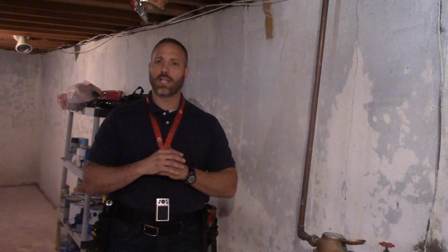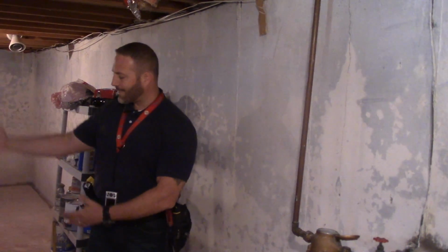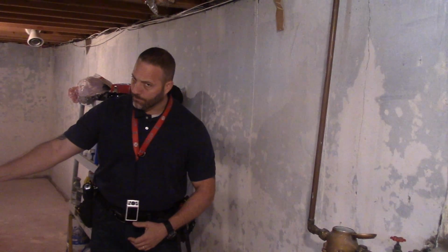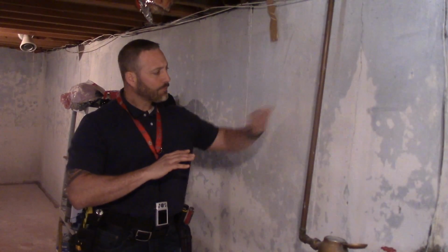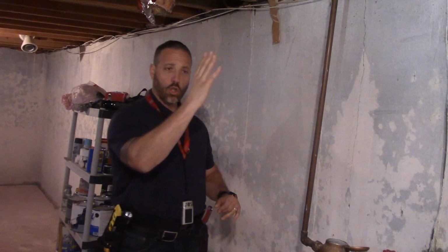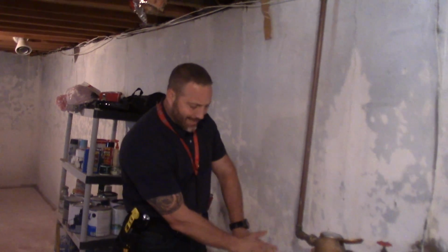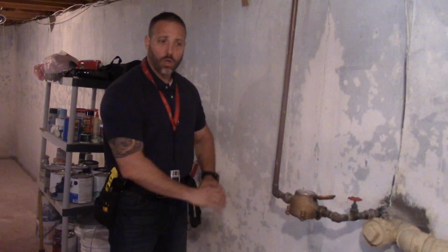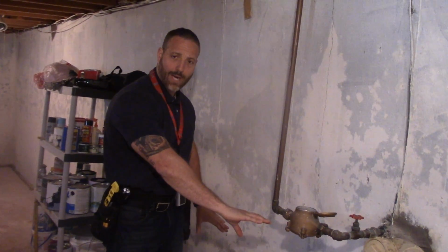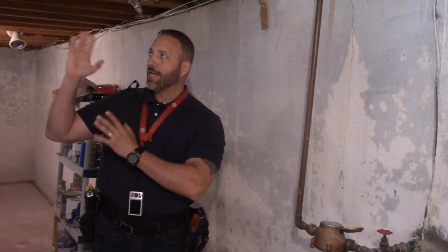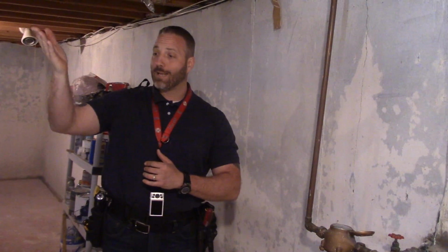Now, there are multiple elements of a basement inspection. First, we're going to be looking at the stair system, the railing system. Then we're going to move on to the sill plate and rim plate. We're going to be looking at the wall along with the window. We're going to look at the joint between the wall and the floor, which typically has a French drain. Thereafter, the next element, we're going to be looking at the joist and the floor structure, the main beam along with the main post, and then we're going to be ending with the sump pump.